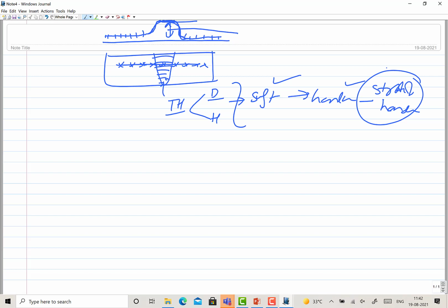In most of the cases, they show hardening, and that is why whenever the steel or the copper alloys are joined using solid state joining process, invariably they show the joint interface is harder and stronger than the base metal. Okay, especially in these autogenous solid state joining processes, unless we use some kind of interlayer. Interlayer will be facilitating the metallurgical compatibility, but may be weakening also at the same time.